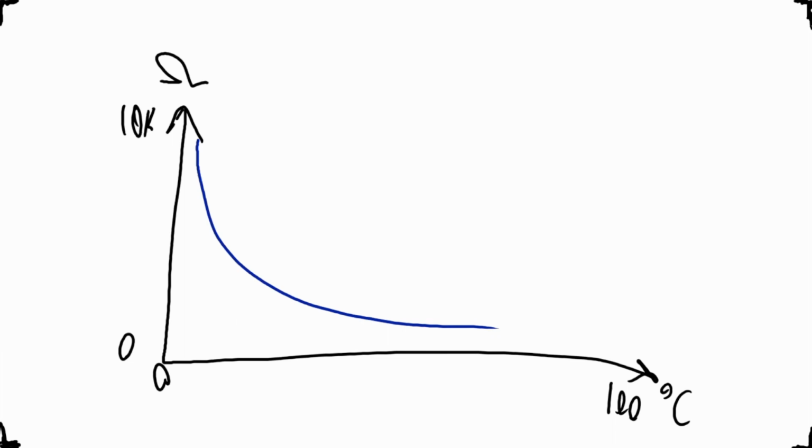Now, with the circuit that we've made, a voltage divider, which in turn translates the changing resistance into a changing voltage, as the resistance of the resistor is increasing, the voltage that would be dropped across the resistor is also increasing, which then leads to an inverse proportionality relationship, where the voltage that you would see on the resistor, measured in the red here, would be roughly an inverse version of the graph of the resistance here, where this red value here is the voltage across the resistor.